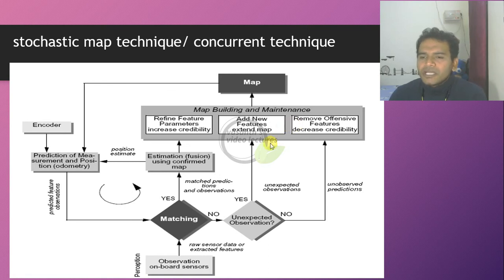Then, for example, if you are moving on a very uneven terrain, that terrain data can be added as a new feature. In certain cases certain features are not needed. For example, in a mobile robot, if the sensory data is Z, which is generally not required and continuously feeds data about the Z axis, that data can be decreased or completely removed.